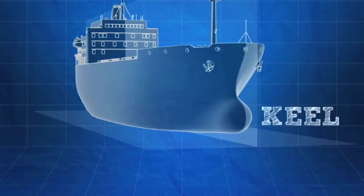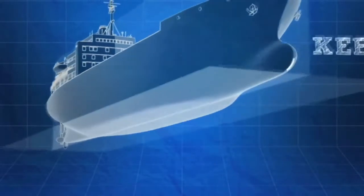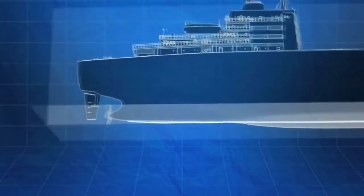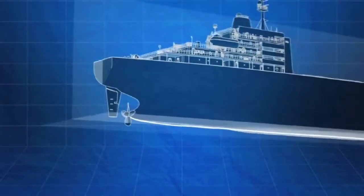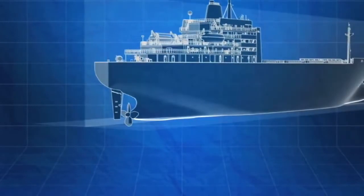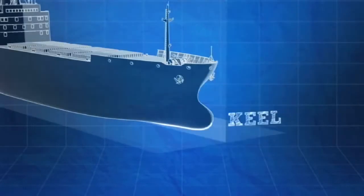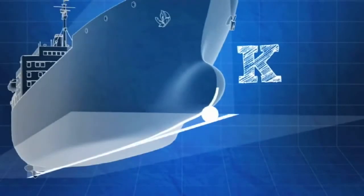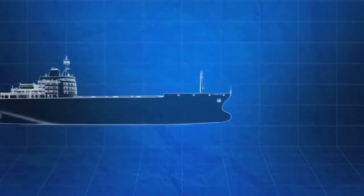The keel is the principal structural member of a ship, running lengthwise along the centerline from bow to stern, to which the ship's frames are attached. The lowest point of the keel, or K, is the point from which vertical distances are measured on a ship. K is located at the intersection of the centerline and the baseline.